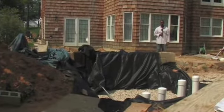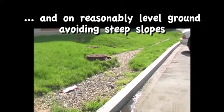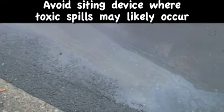Additionally, infiltration devices should be situated on level ground, void of steep slopes or previous excavation. Infiltration sites must also be free of spills, toxic substances, contamination, or ongoing groundwater remediation.